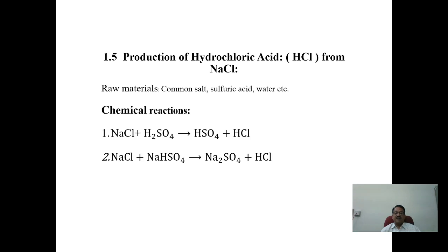In the other method of production, hydrogen and chlorine are combined and made to react with each other in a reactor in the synthesis process, and the hydrogen chloride gas obtained is absorbed in water in carbon lined or plastic rubber lined reactors, because hydrochloric acid is a highly corrosive liquid.